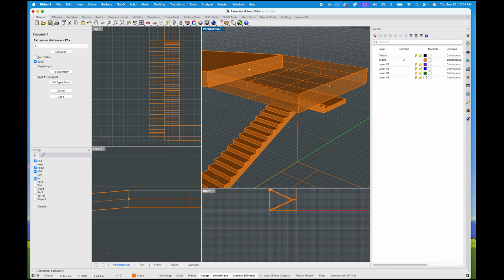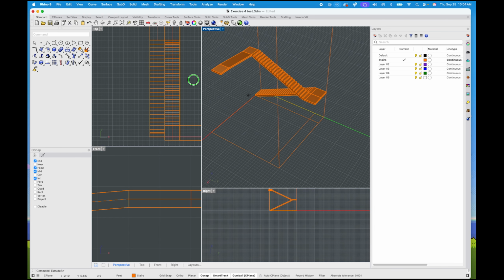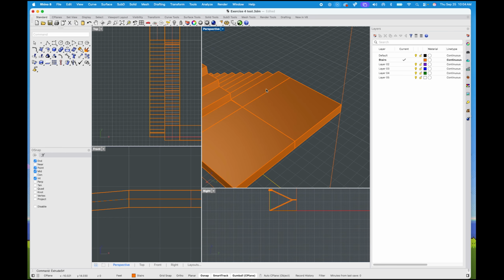And we'll go out again, say another 4 feet. Now, one thing that I haven't expressed yet, and you probably heard this in studio before, but really landings should be at minimum the same distance as the width of your stair. So if you have a 5-foot stair, you need a 5-foot depth of your landing, right? Just in case you didn't know. Now, to be fair, it can go infinitely, right? I mean, well, there's not infinite amount of material, but I digress. It just needs to be at minimum the same as the width.